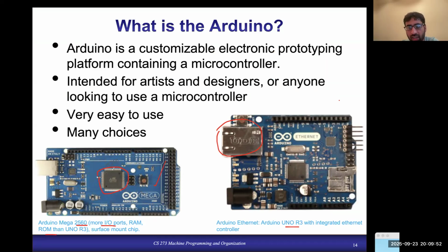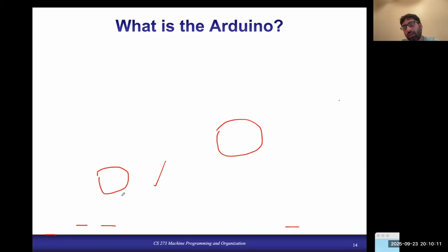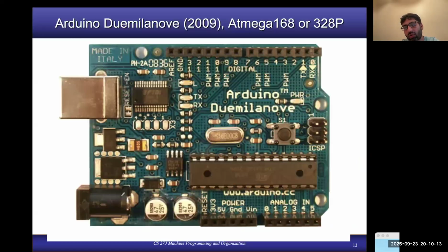So they are more compact. They take much smaller space as compared to the DIP packages, but they are not good for prototyping because, for example, you cannot directly put them on your breadboard when you are building a circuit and you want to first test your project. So if you are developing a product and you first want to prototype it, you will use the same microcontroller but with the DIP packaging.